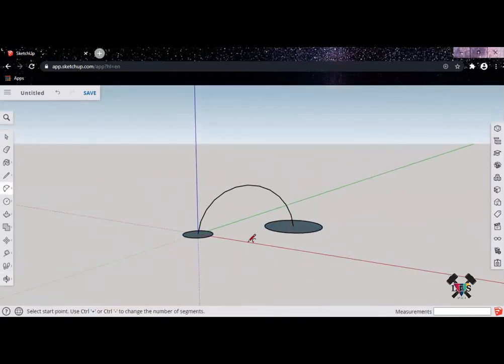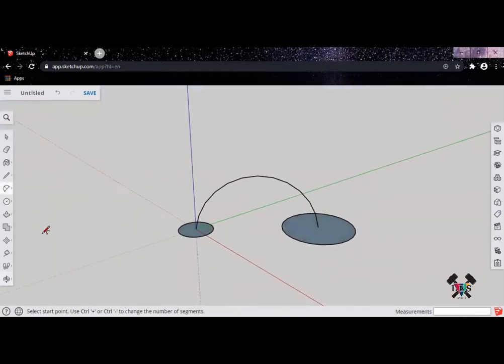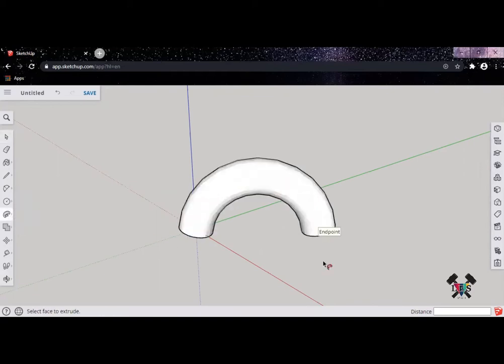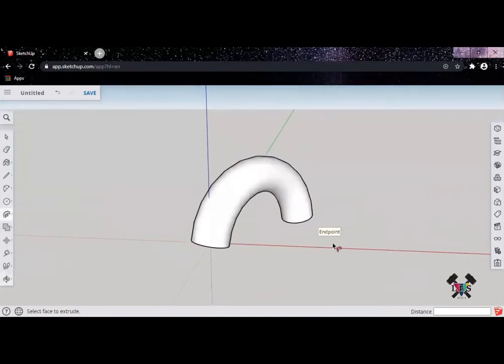It'll make an arc length, and if you press under this push/pull button, there's a thing called Follow Me. If you click it, you can just follow this line. Sorry, one thing I forgot to mention is that you have to delete your old thing. It has to be freed for it to work. It's kind of self-explanatory. And it just follows and creates an arc like that.